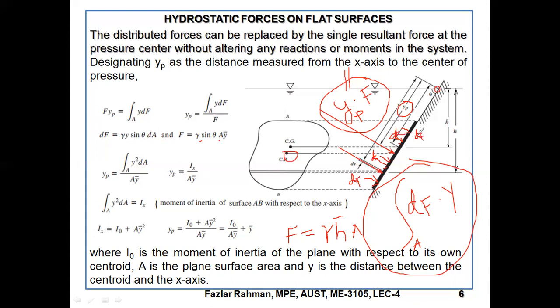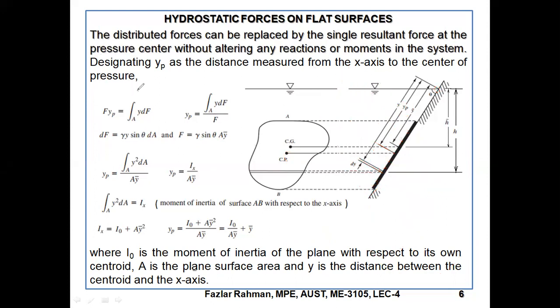So how much will be the moment here? dF into this distance. For this force, dF into distance. If the distance is y, then we can say dF into y, and then we take the integration over the area. That's why we are saying this term and this term are equal.